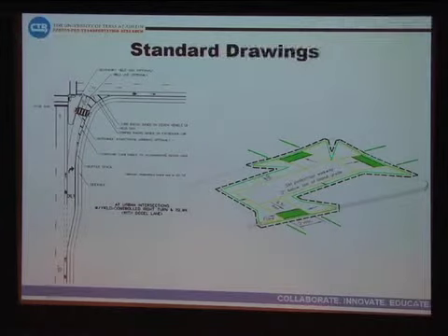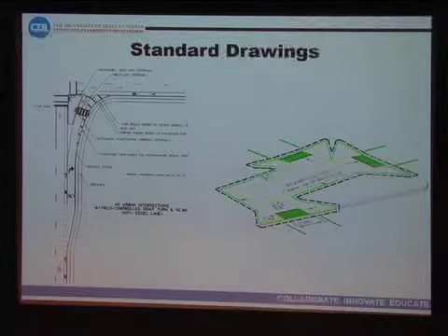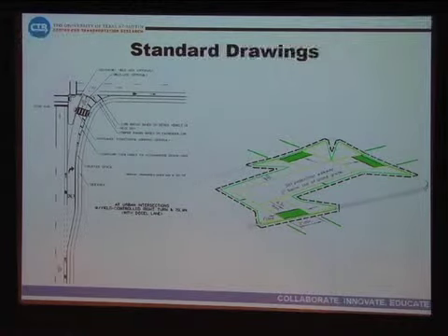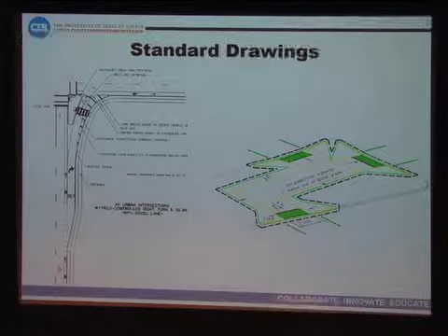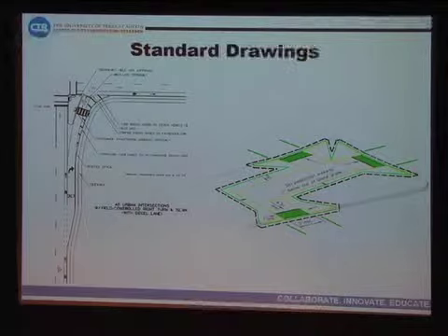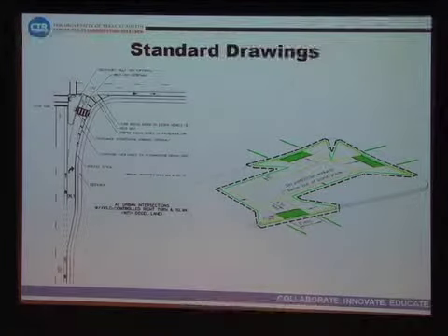So one of our TxDOT representatives came up with sort of a hybrid concept to raise the walkway to about 2 inches below the top of curb elevation, so we achieve the raised pathway to get away from some of the drainage issues and debris collection. But we're also providing a channelizing pathway as well to help with wayfinding for those with disabilities.